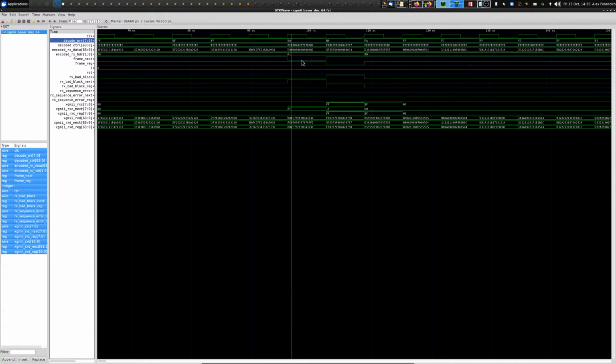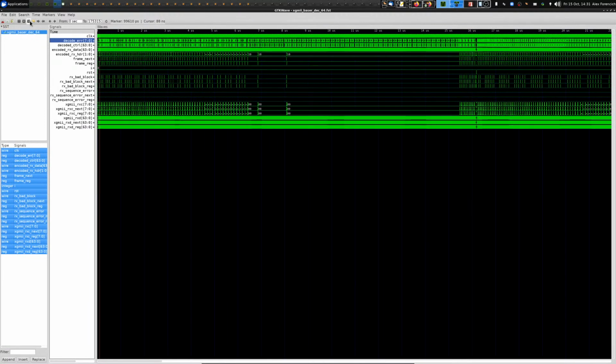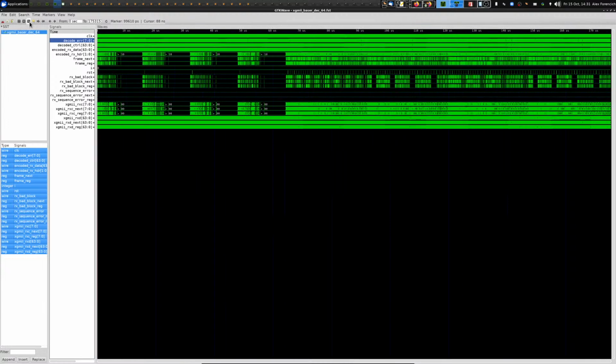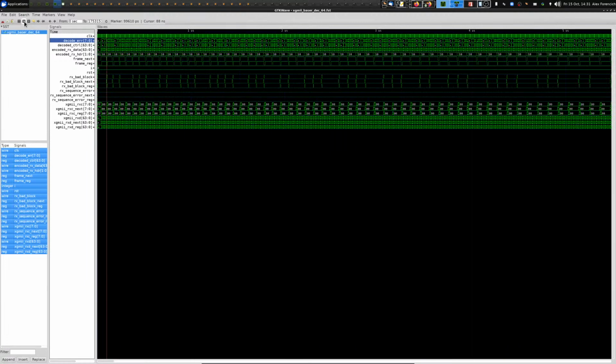That is a test bench problem that I will have to take a look at. So that indicated a decode error, and that was passed through because that control character was used. Well, I would expect that to be low the whole time, but all right. Test bench problem, I will sort that out later. But the frame does appear to be working correctly.